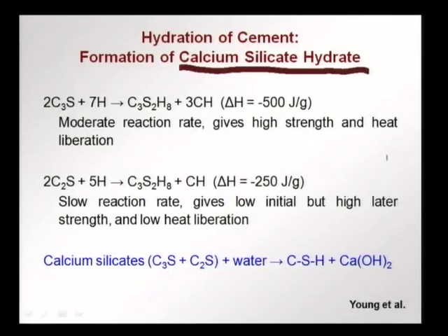Secondly, we have a higher amount of calcium hydroxide produced in the first reaction, and calcium hydroxide is sort of a weak link in the hydrated cement paste. It does not offer bonding behavior, and in terms of durability it reacts more easily with other compounds and gives rise to durability issues. So, we have to be very cautious when we go towards cements with very high C3S contents, and it may not be necessary or advisable in most applications.